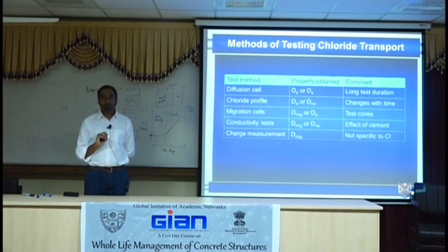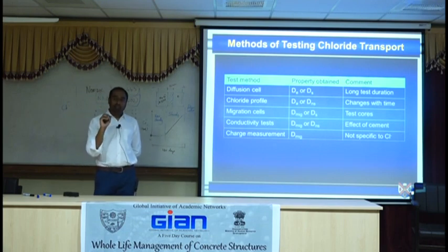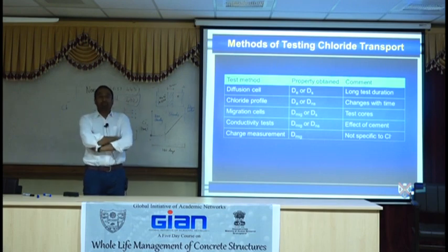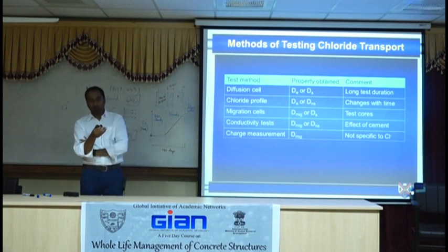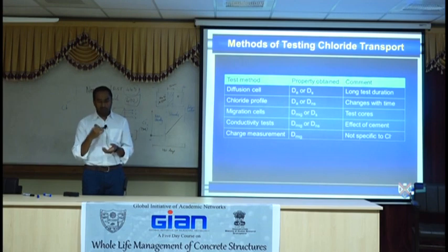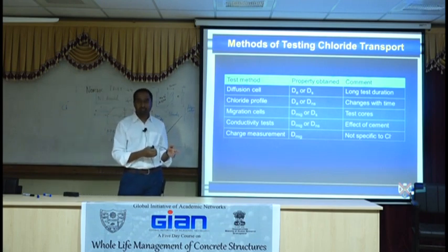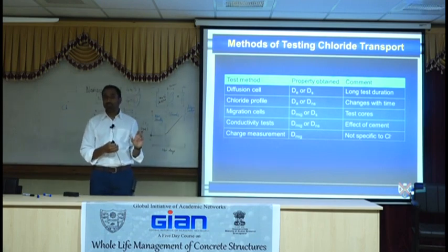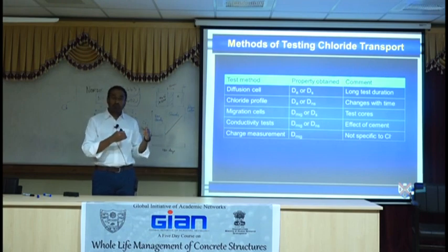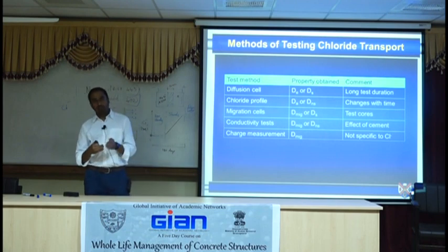Strength cannot be used as a performance indicator for durability. For the same fact, remember the pervious and the non-pervious concrete. They can be the same strength, but the flow will be completely different. The answer lies in what is in the cement matrix that they used to get that M40. If they use slow reacting, high replacement material to get that M40, I don't even know if M40 is a 28-day strength or 56-day strength. Even that might change the story. So if they use a high volume replacement concrete to get to the M40, then highly likely that concrete will perform better.